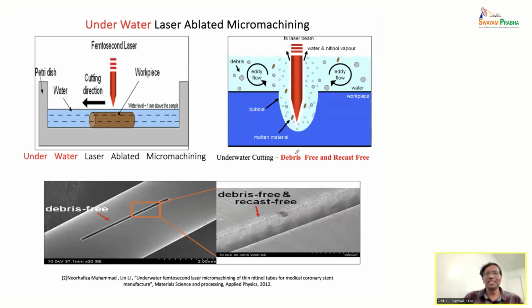Another interesting phenomenon is that when you change the media, usually it is air, but if you machine a component under a different media like water, we found that the finish improves, the heat affected zone has significantly decreased, and the quality of the hole has increased.